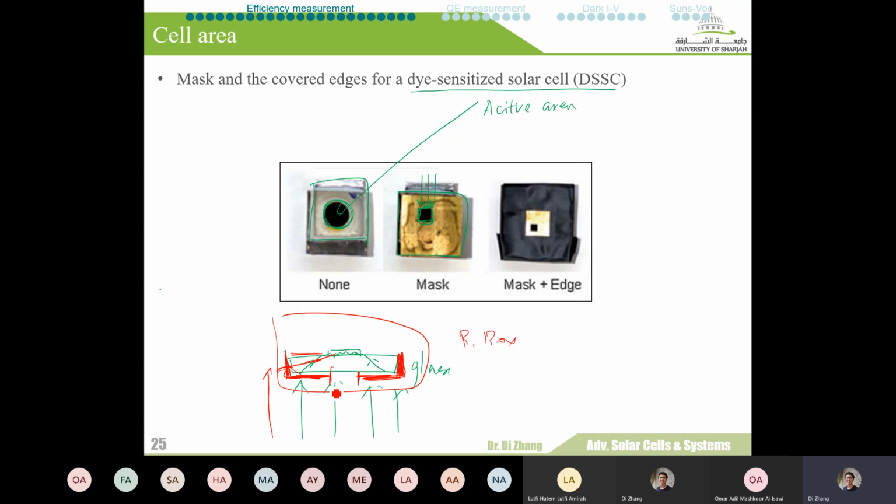So any losses happening inside are your problem. This is the solar cell's problem, not the measurement setup's problem. The additional problem is that if we have the black box here, but the black box is getting more irradiance than the 1,000 watts per square meter, then we consider this a measurement error. I just want you to understand that we're talking about slightly different things here.